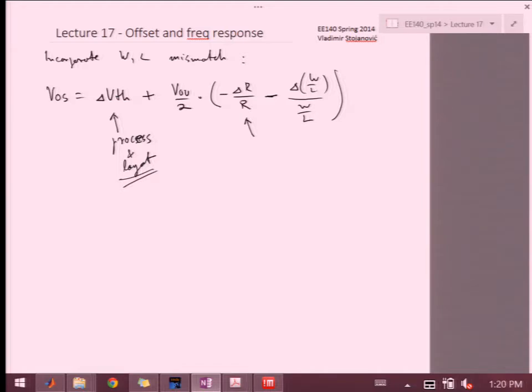That strain depends a lot on the patterns around the transistor. So if you put a different pattern in the layout around a particular transistor, even though they're exactly matched in size, you will have a different threshold voltage. And that effect is now starting to be much more dominant than, let's say, random dopant fluctuations.